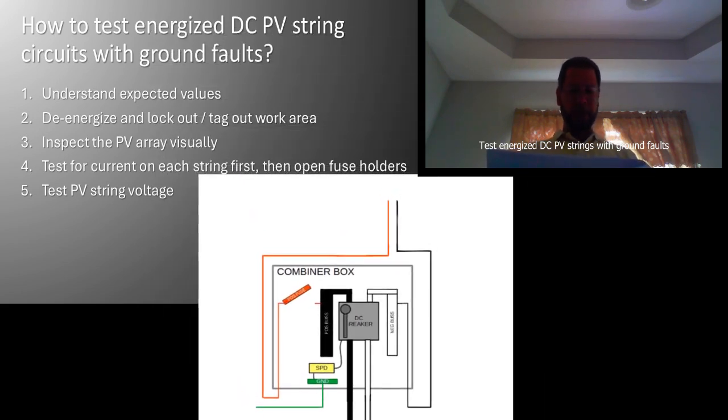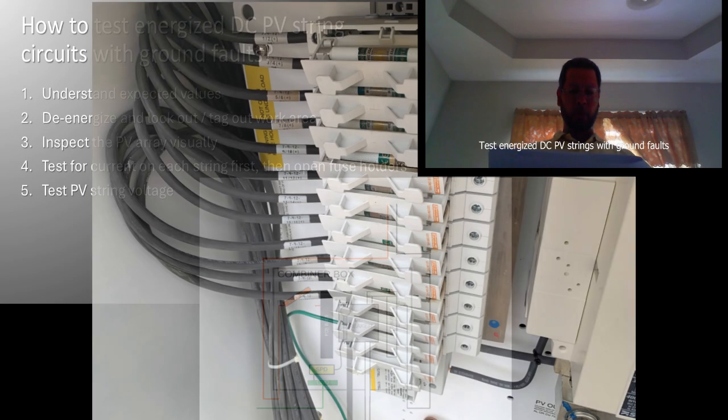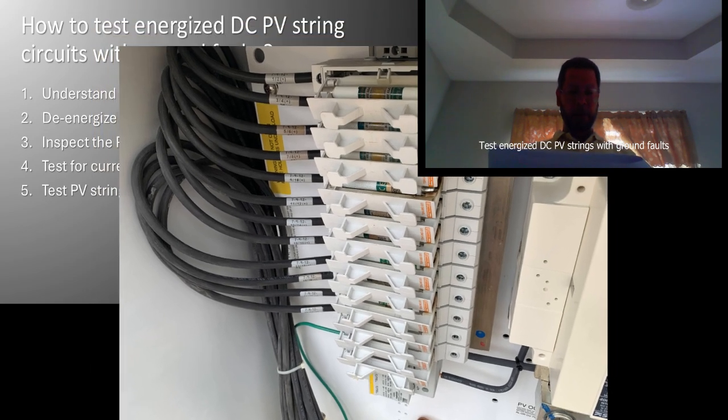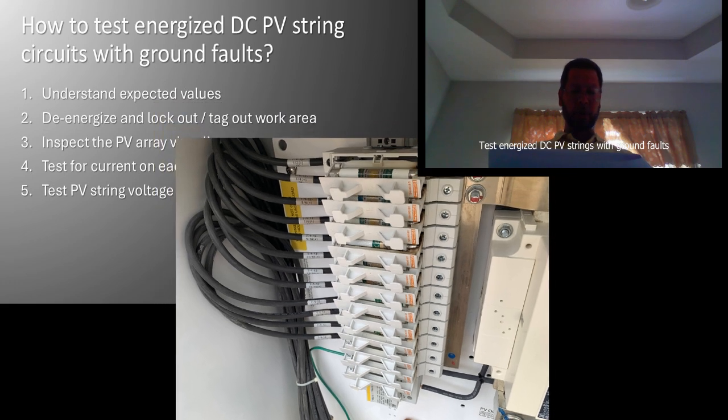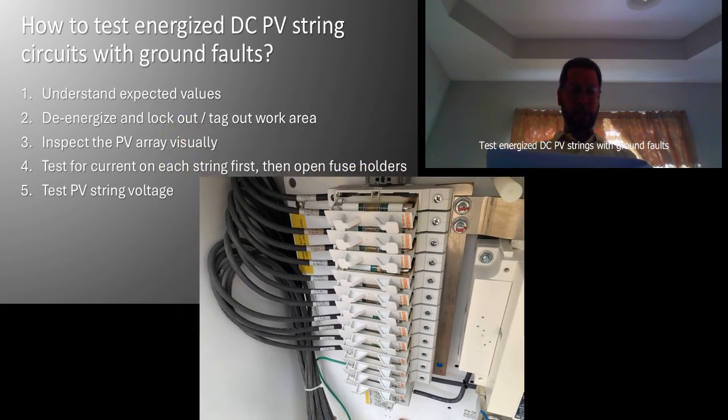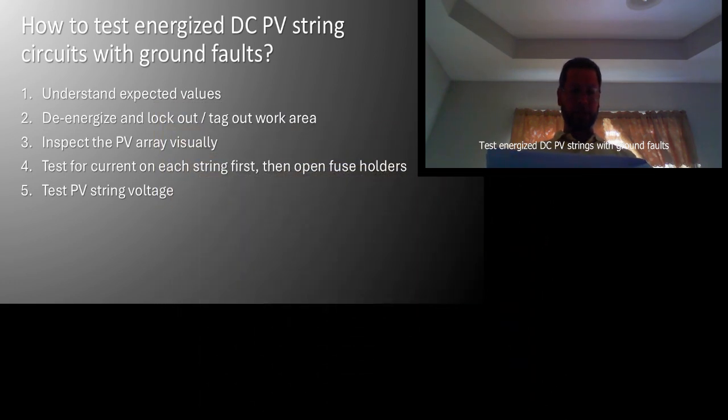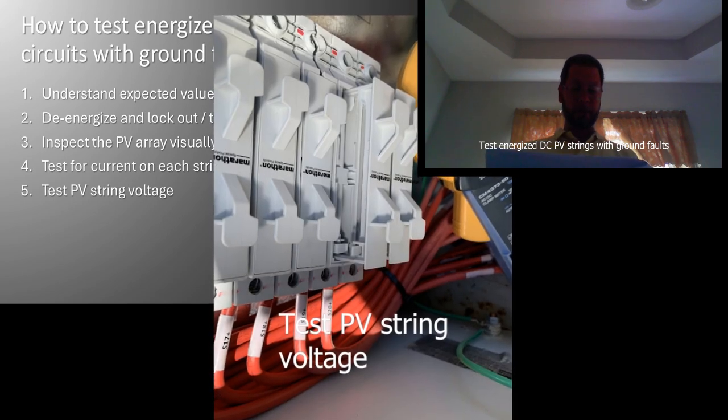Warning: never measure current in a PV installation with the probe tips of a multimeter. This will cause short circuit current to flow through the multimeter, which may damage the meter. It also creates a safety hazard when you remove the probe tips from the terminals you're testing.